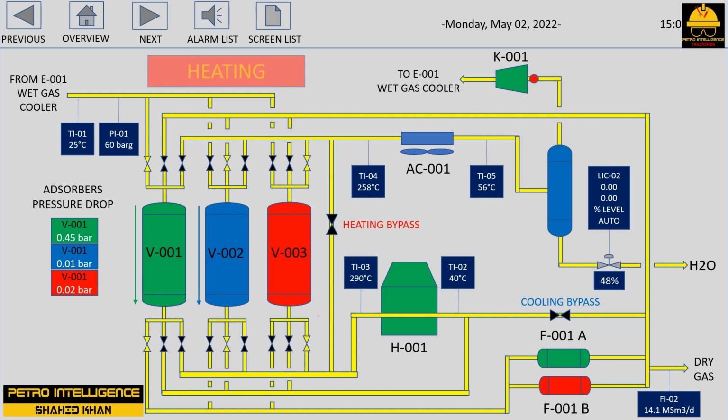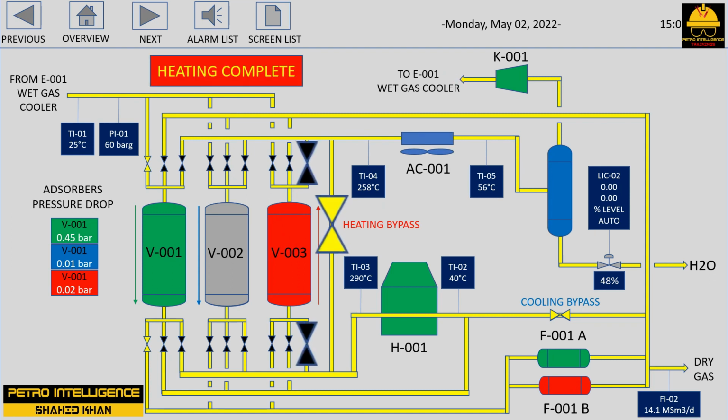If we pulled samples from different points through the bed and measured the amount of the impurity in each, we would find that for the first portion of the bed, the impurity level would be as high as it is in the feed. Then we would come to a point at which the impurity content dropped off very sharply in a relatively short distance through the bed. Beyond this point, the impurity level would drop off slowly again to essentially zero.